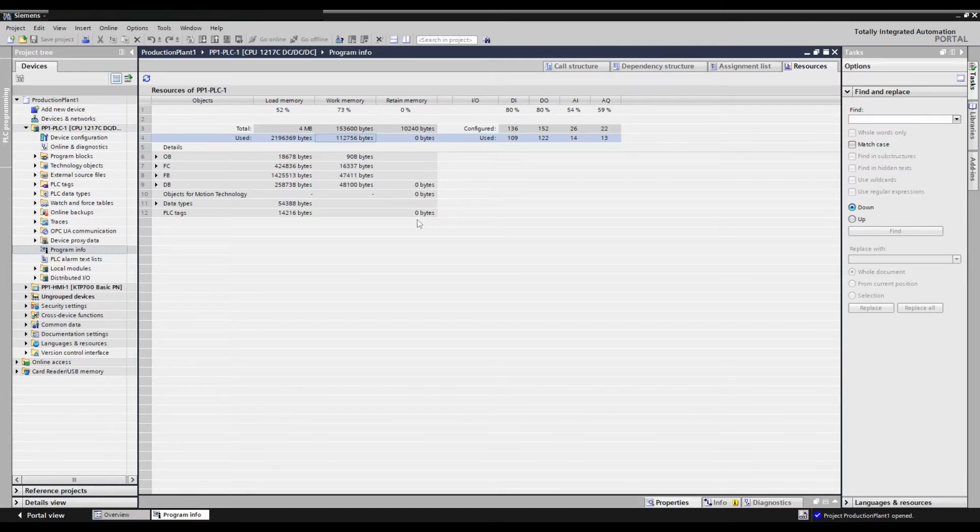Of course, the other interesting question is how quickly can a program execute on this 1200 series PLC? Well, I won't start it up now, but the cycle time is about 100 milliseconds, which is, in my opinion, horrendously long. But these PLCs are not high-end PLCs.